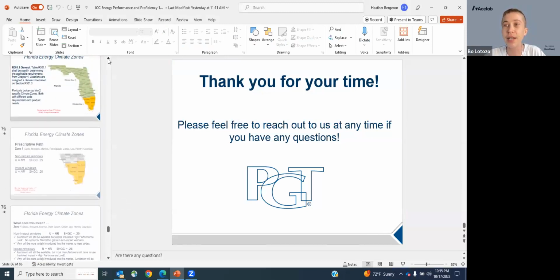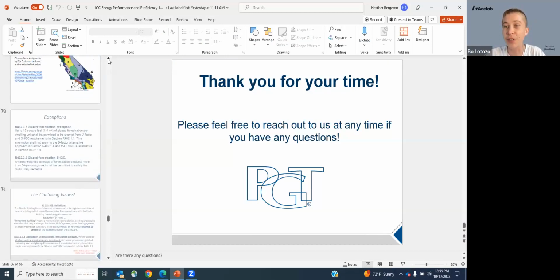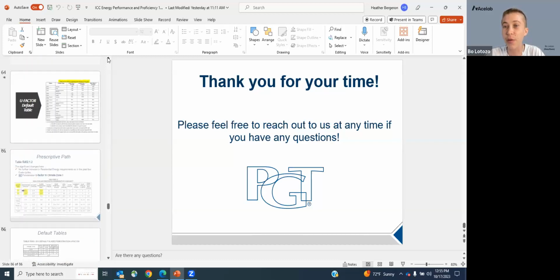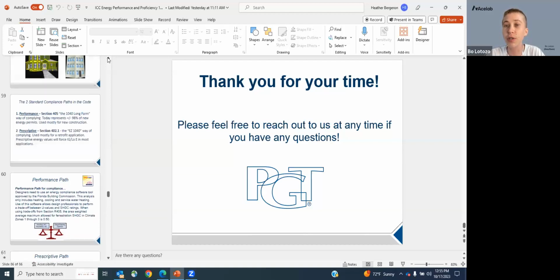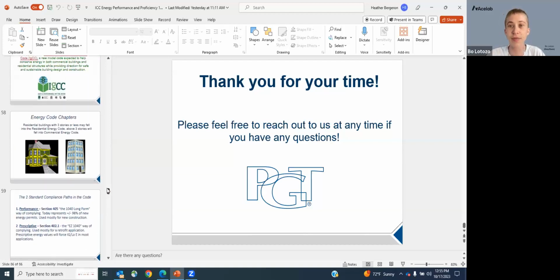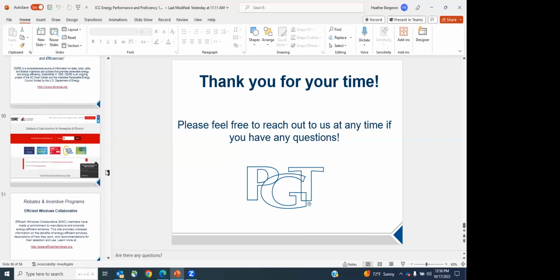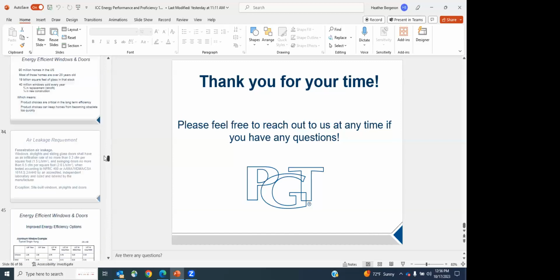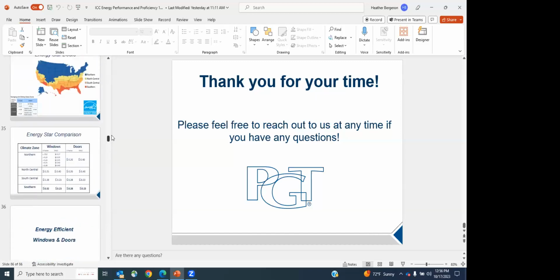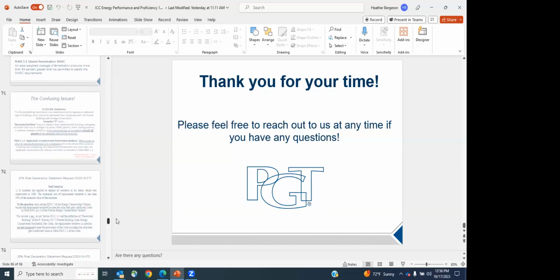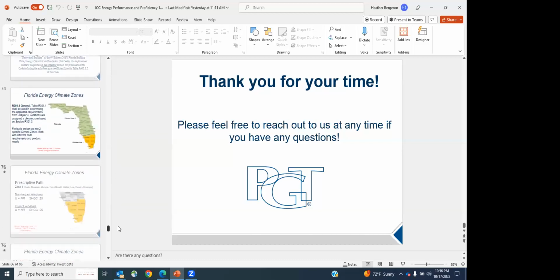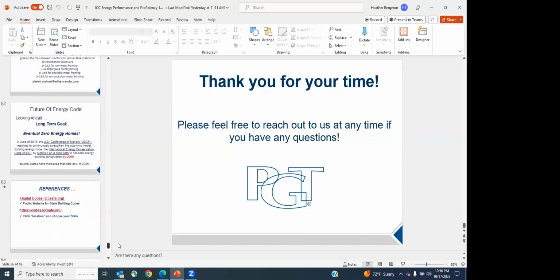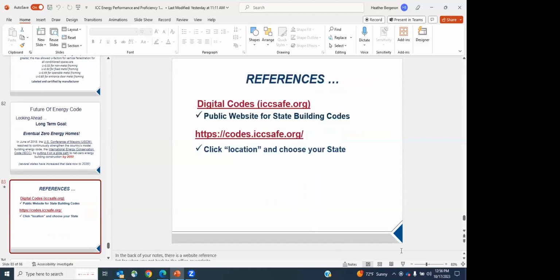All right, let's see. Addison has a follow-up question. First, thanks, Jim. Quick follow-up would be, can you reduce the UV light transmittance with a lower VT value? I assume there are multiple films to apply to the glazing. Yeah, I'd be very, very cautious in that. The reason I say that, what a lot of people don't realize, is when you take an insulated window and you put a film on it that's put on the inside of the home, in many cases you want to check with your manufacturer, because most manufacturers now are going to void the warranty.